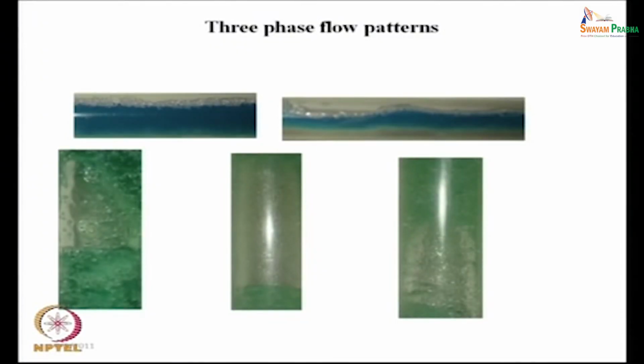Okay. So, certain other things, well, the next thing I thought I will show you is how the flow patterns evolve and how important it is for us to know the different flow patterns. We first found out air water or vapor liquid, it is more or less the same. Then instead of water we tried to introduce oil, we found out how it changes. We changed the property of the oil, we found out how the flow pattern changes. The tendency of core annular becomes more, and that is an extremely fortunate situation.